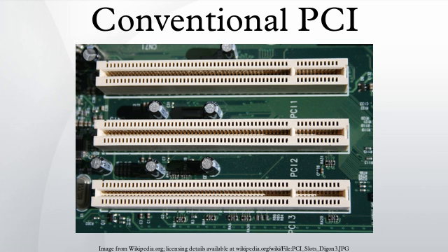On the rising edge of clock 0, the initiator observes FRAME and IRDY both high, and GNT low, so it drives the address, command, and asserts FRAME in time for the rising edge of clock 1. Targets latch the address and begin decoding it. They may respond with DEVSEL in time for clock 2, 3 or 4. Subtractive decode devices, seeing no other response by clock 4, may respond on clock 5. If the master does not see a response by clock 5, it will terminate the transaction and remove FRAME on clock 6.